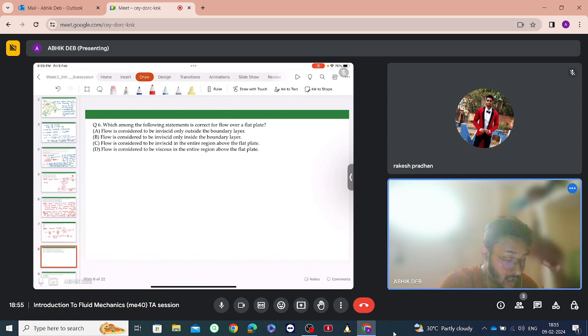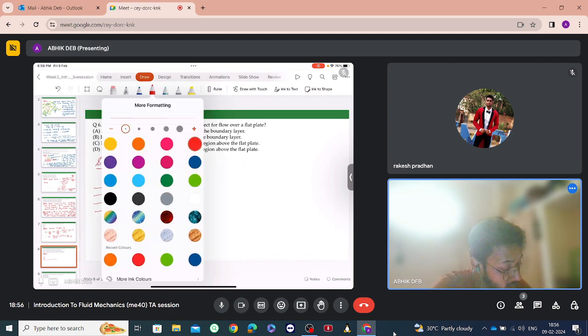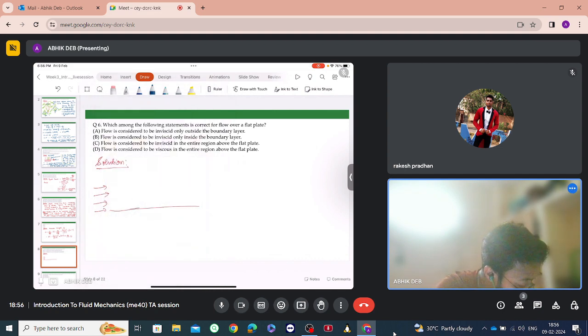So why is the boundary layer formed basically? So this is a solid, and the fluid enters and starts flowing over this solid, and what happens is, because of the no slip boundary condition, the tangential velocity at the point of contact becomes zero. That is, this layer of the fluid does not flow. So this has a zero velocity, say.